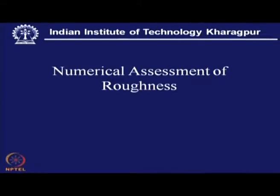Numerical assessment of roughness. This is one important step: how to quantify this surface roughness. We can have a qualitative feeling or impression about the surface, whether it is smooth or rough, but quantification is necessary in order that a correlation is established between the input variables, the substrate preparation, the chemistry of the substrate, the cleanliness of the substrate, and all related issues can be properly addressed if we can numerically assess the surface roughness.